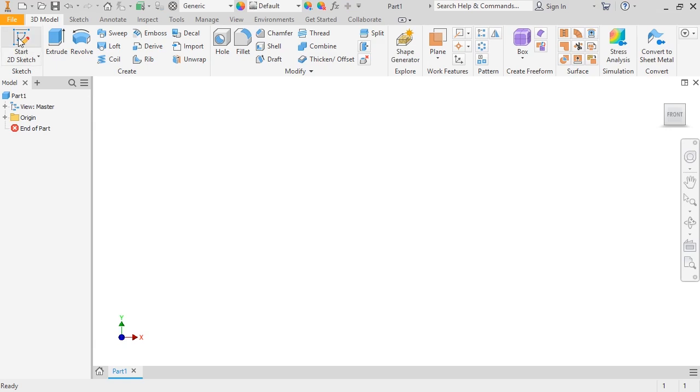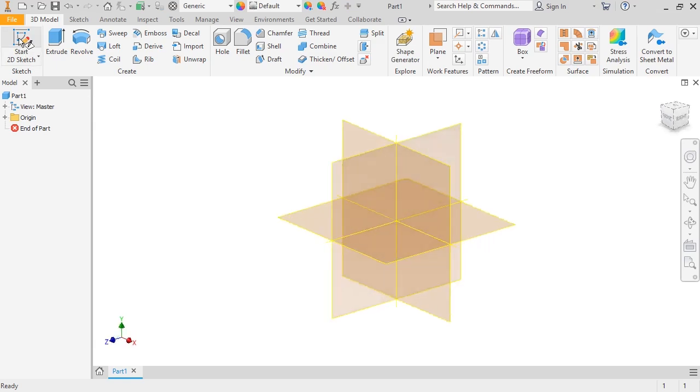Then start a 2D sketch, and now come to my first decision point, picking the first sketch plane. If I choose the XZ plane, I can sketch the rectangle's top face and extrude it upwards to define the thickness. If I choose the XY or YZ planes, I can sketch a thinner rectangle of the front or right side respectively, and then extrude it outwards to add length or width.